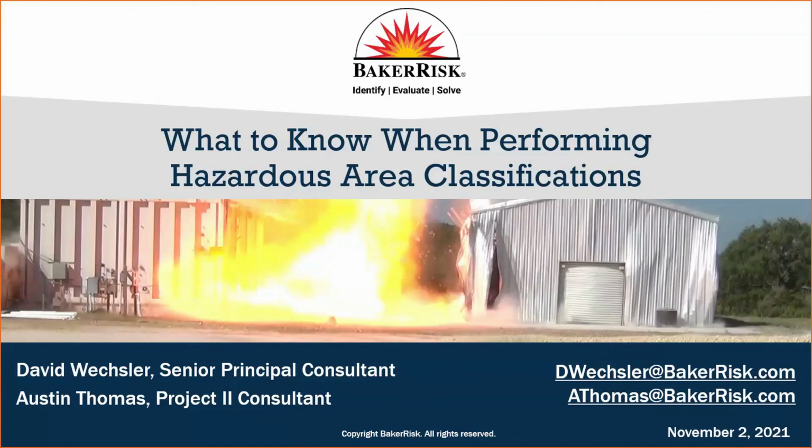So they are different. There have been attempts, I will point out, where some people have tried to utilize dispersion modeling for hazardous area classifications. My experience with that has often been that they pick a size of a hole that's very, very small, and therefore the footprint from the leak is very small, and therefore they would try to use a classification that's not as large as what we have applying codes and standards.